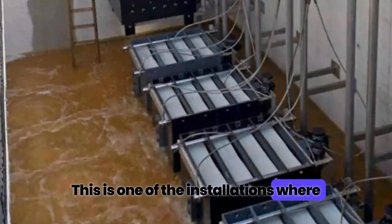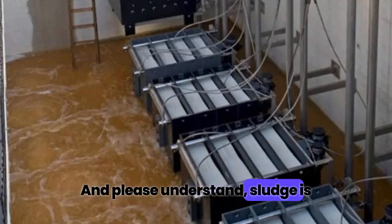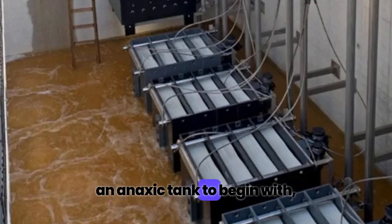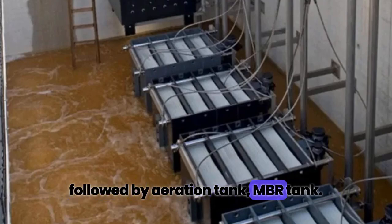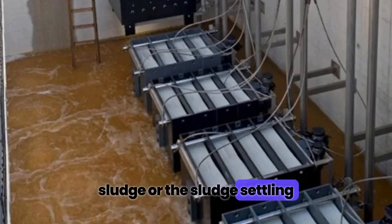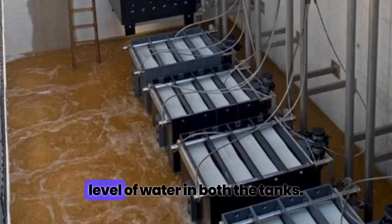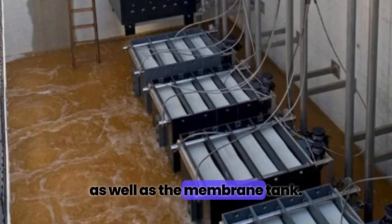This is one of the installations where a separate tank has been used, right? And please understand, sludge is continuously pumped back into the beginning of the process. That means most MBR tanks today have an anoxic tank to begin with: a collection tank, anoxic tank, followed by aeration tank, MBR tank. From the MBR tank, again, the sludge settling at the bottom of the tank is sent back to the anoxic tank. This is a continuous loop process. Also, you need to maintain the same level of water in both the tanks, the MBBR or aeration tank as well as the membrane tank.